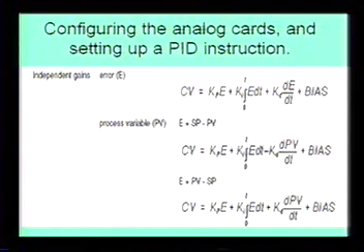But typically, if your valve, your control variable, goes from 0 to 100% and it changes states within 3 seconds, you can control this thing like no problem at all. And if your process is designed right, you've got the right amount of flow coming in and the right amount of flow going out, and the control variable, in this case the modulating valve, is about 75% open, and that's about a perfect balance for this system, then you should be able to control not all upsets, but certain disruptions